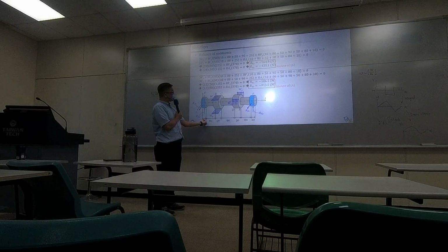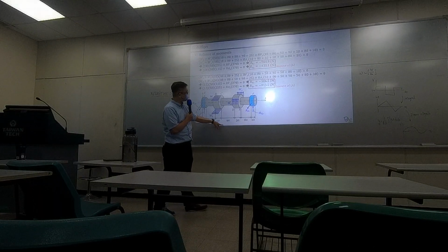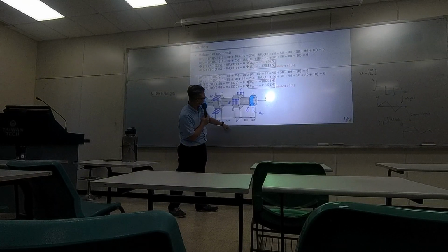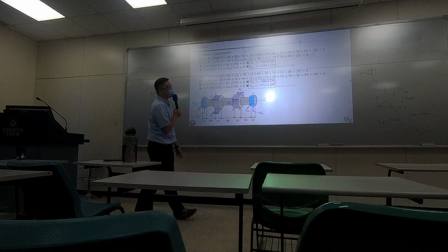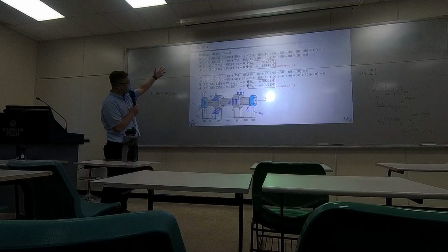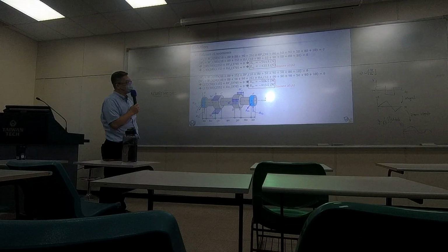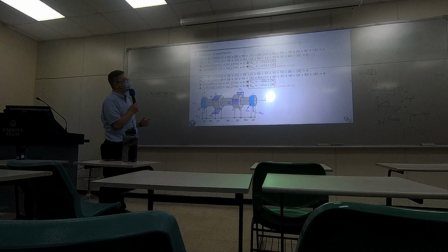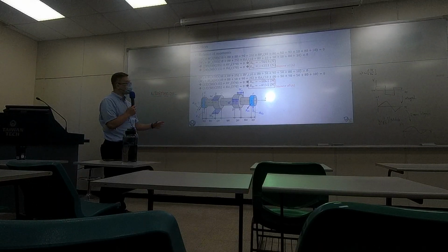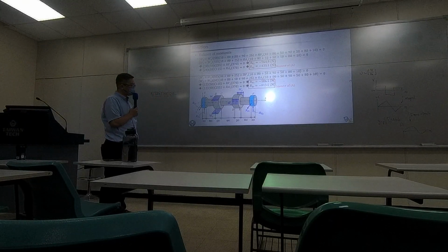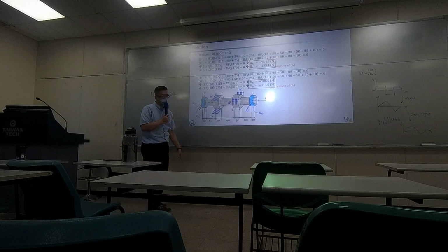So position 10 plus 90 plus 80, 50, 90, 50, 80, and then 10. So that equals 0. Similarly, you derive the other three equations. It turns out all the reaction forces are negative. So basically, on the opposite side of the arrows that I have drawn.